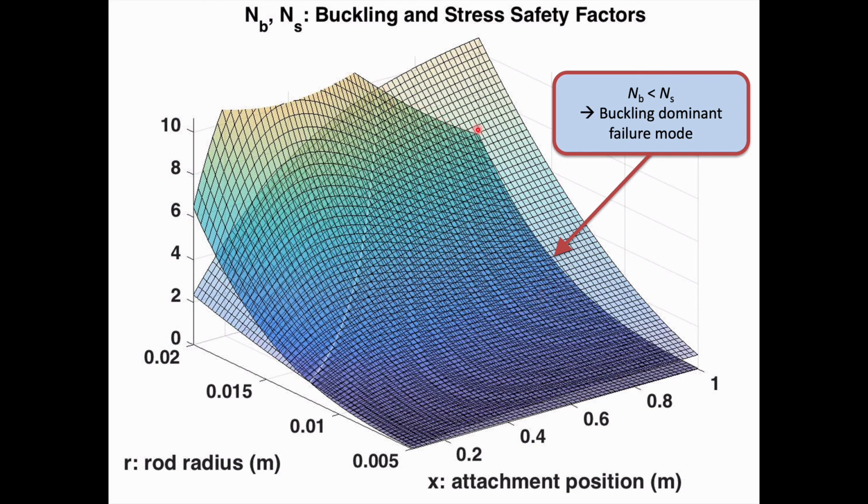So it's this surface I'm tracing the edge of right here that is underneath the other one. This surface corresponds to the buckling mode. So if I had a design right here, and if I started applying a load, I'm thinking in terms of which surface would I hit first as I move vertically. I would hit the buckling mode surface first. So that's the dominant mode.